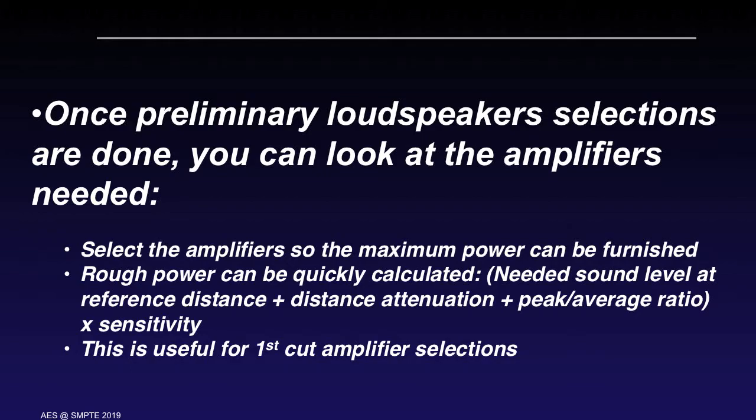Most amplifiers talk about output power in terms of the power for a sine wave input, which has about a 3 dB peak to average ratio. In fact, it has an exact 3 dB peak to average ratio. The AES amplifier spec uses a 6 dB peak to average pink noise. SMPTE now has a standard pink noise, which is generated by a Python script in ST2095-1, 2015. Use the correct factor to determine how big the amplifier should be.